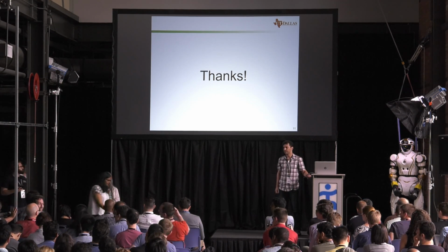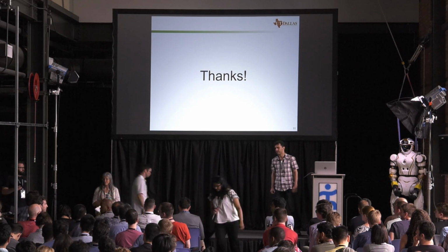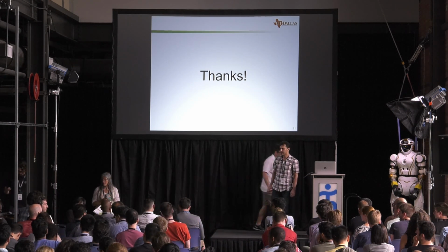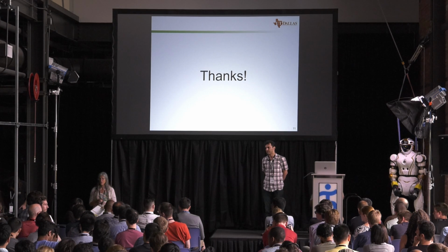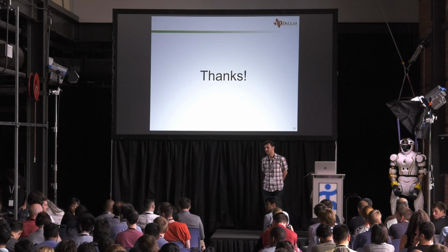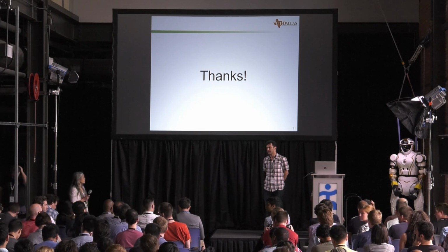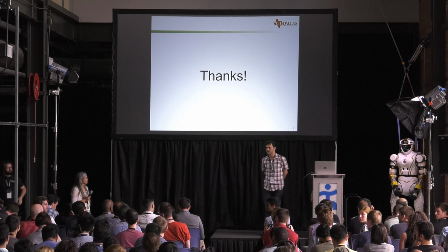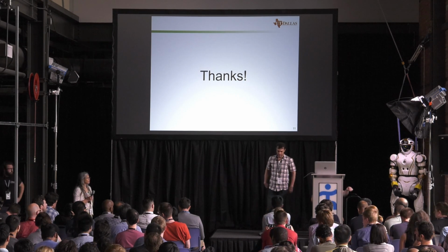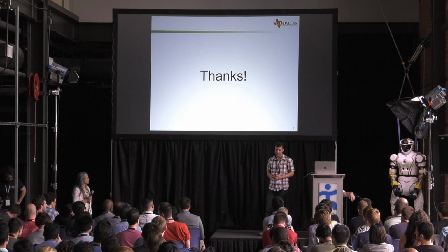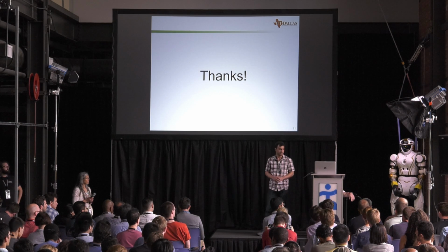So you didn't want to get into the mathematics of why the holonomic controller becomes singular near push-off and touchdown, but that generally represents either a loss of information or a loss of actuator freedom or some other loss of control capability. So what structurally is involved without the math?